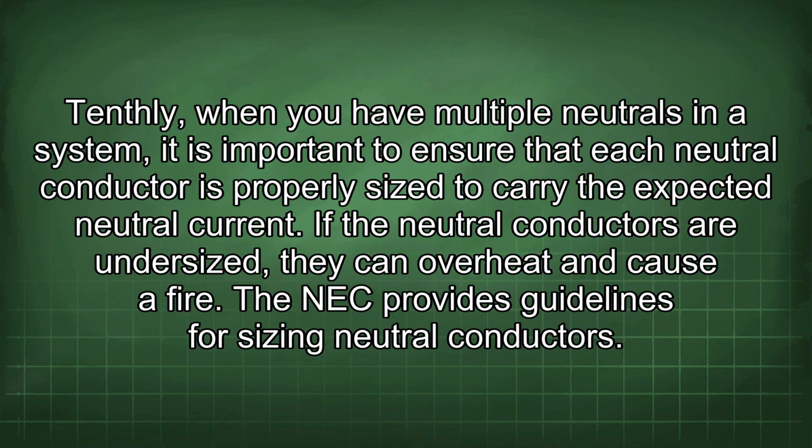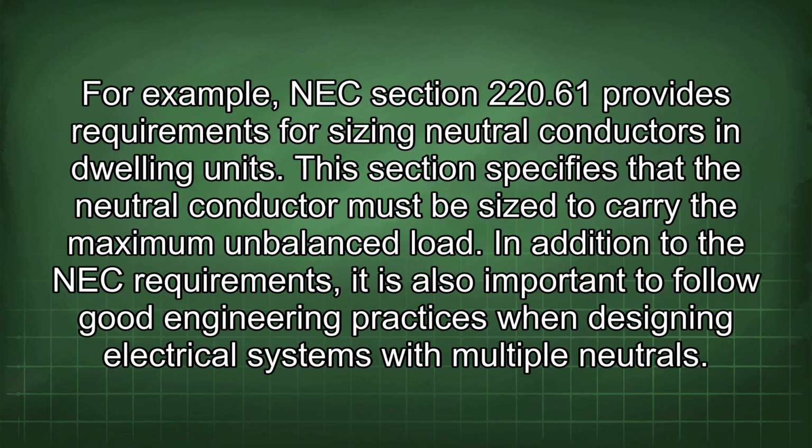Tenthly, when you have multiple neutrals in a system, it is important to ensure that each neutral conductor is properly sized to carry the expected neutral current. If the neutral conductors are undersized, they can overheat and cause a fire. The NEC provides guidelines for sizing neutral conductors. For example, NEC section 220.61 provides requirements for sizing neutral conductors in dwelling units. This section specifies that the neutral conductor must be sized to carry the maximum unbalanced load.